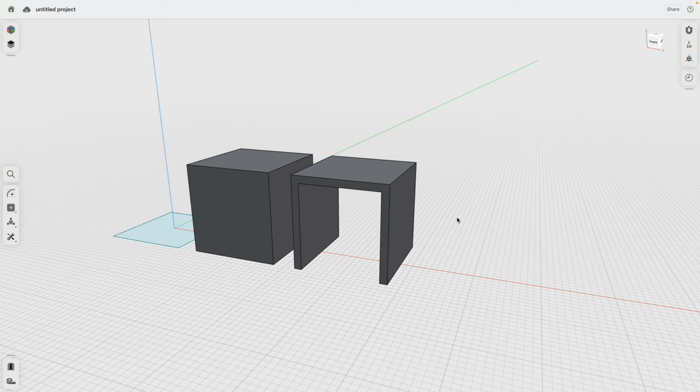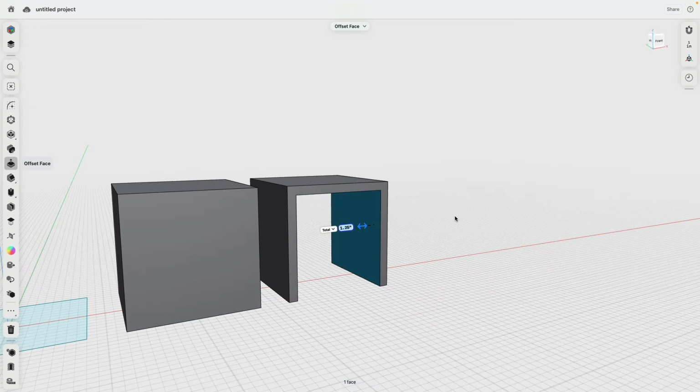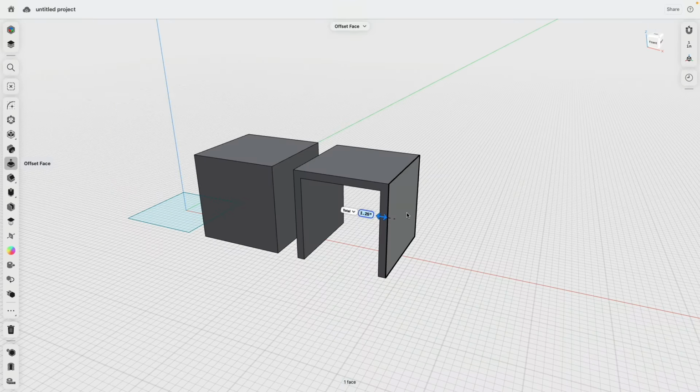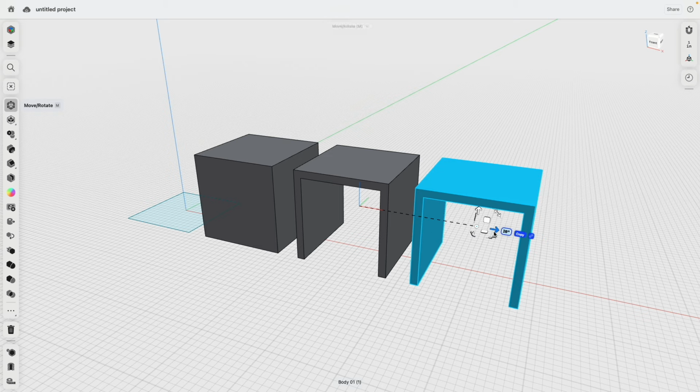One thing you will see through this exercise is actually how I'm building in various steps the design. I block things out very coarsely and then step by step add all the details. At the end, you will see we created everything just from one rectangular sketch. So when I would build this in the woodshop, I want to have a nice flat top surface to sit on, and then under it, I mount the sideboards. Currently, this is all one piece. So let's double click, make copy, and move this over 20 inches.